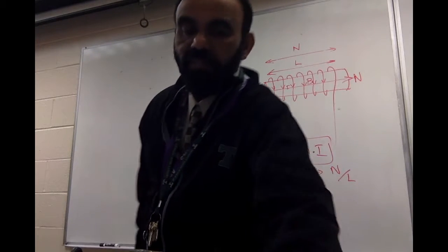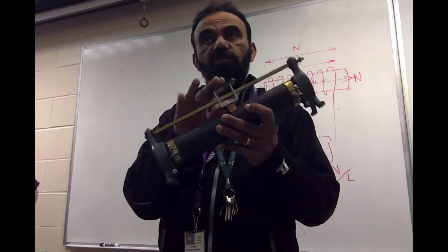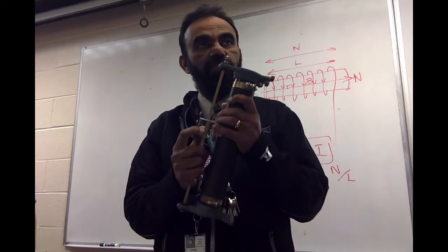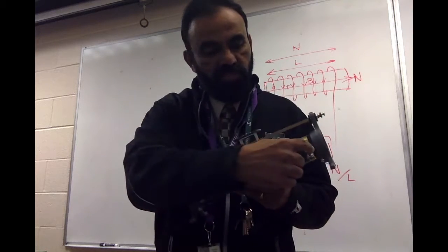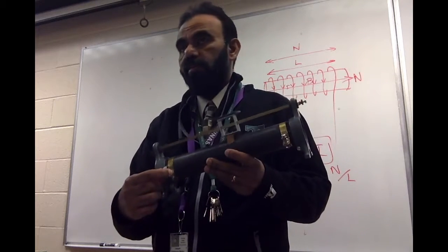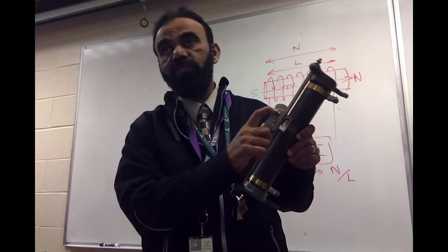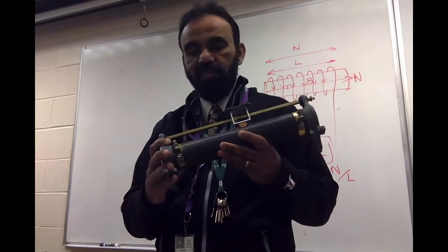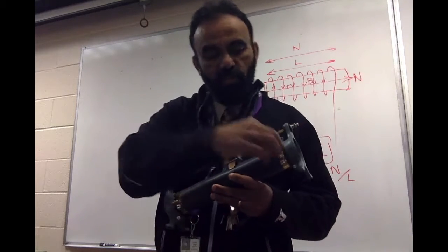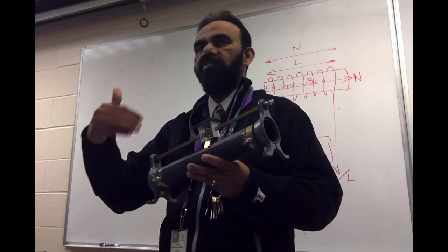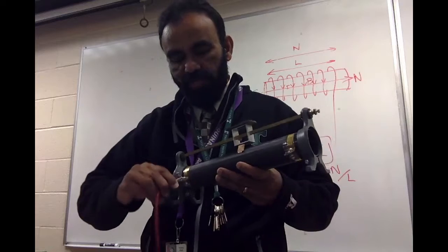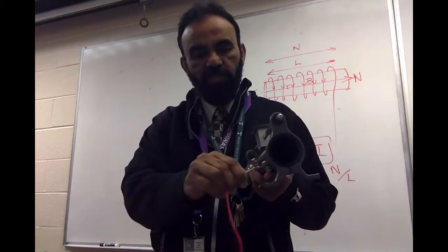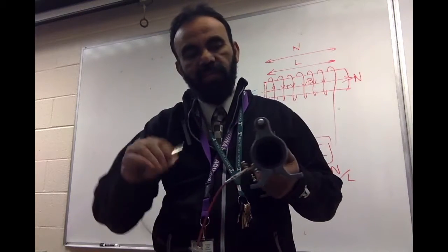Okay, so I'll try to show you that. So this is a rheostat. The main purpose of this rheostat is to control the current flowing in this. The total resistance from here to here says 89 ohms. If I connect a wire from here to here, I'm just including a fixed resistance of 89 ohms. Instead, I'm going to connect it between here and here.